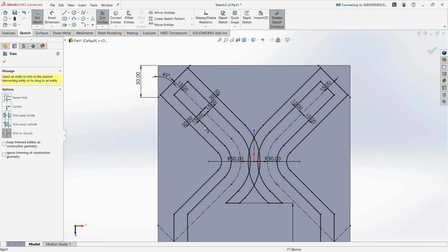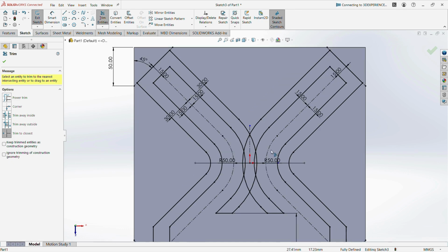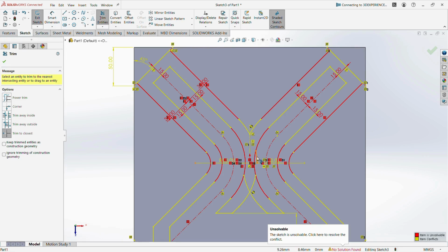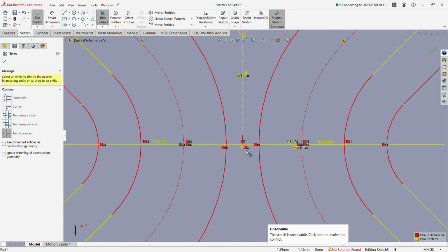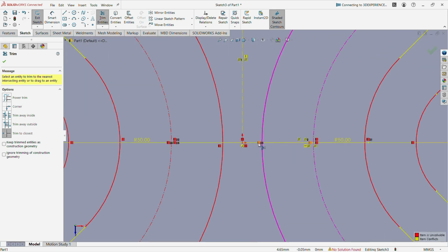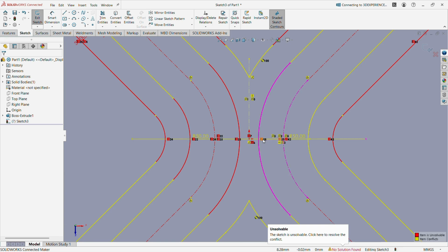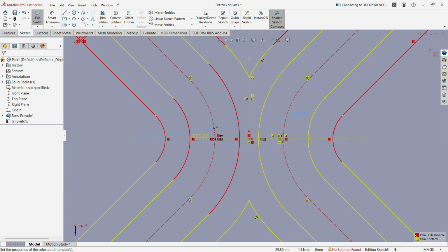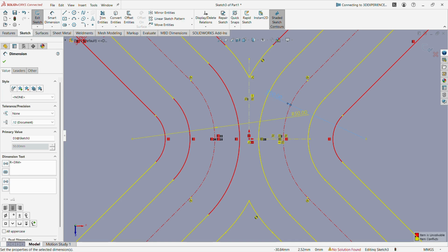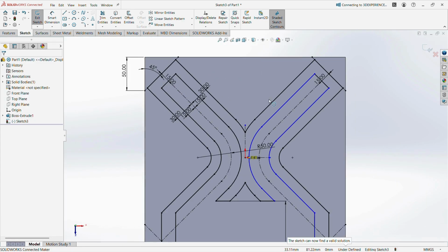Once it is completely removed, also remove the excess portions at this intersecting area. If you just remove these entities, automatically we get this kind of error. Don't get confused. Remove whatever excess entities first, then choose these offsetting portions, select them and delete them now. Offsetting is the primary error. Also, the additional one is the numerical values. Once you delete these portions, now I am going to delete this offsetting value of 50 mm radius. Same as the opposite portions.